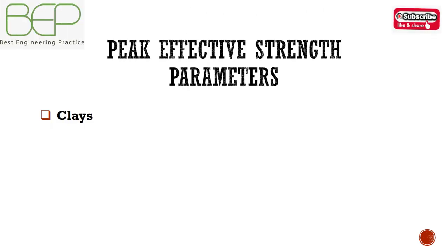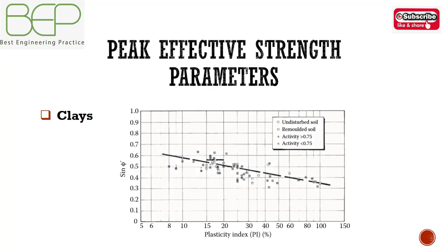In the absence of any triaxial data, the angle of friction can be estimated from the plasticity index from results by Kenney in 1959. The methods described give effective strength parameters for failure in triaxial compression conditions. For clays, the difference is thought to be slight, however, so that triaxial values can be used with confidence since they will be on the safe side.